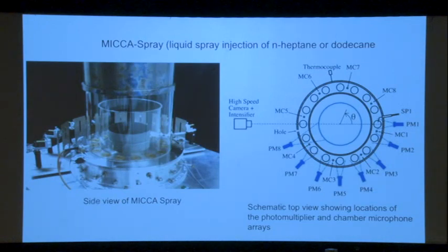So each spray, because it's 16 injectors, each spray is a small spray. It's not much material that is being injected, and so that's a difficult problem. You need hollow cone pressure atomizers which produce a hollow cone, and there is only one company in France which is capable of producing these very tiny little injectors, but they produced it for us. It's not cheap, but that's it.